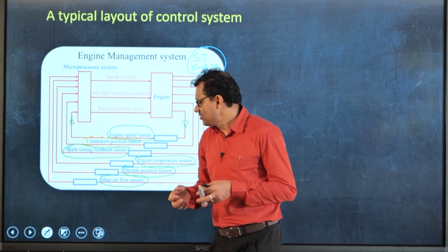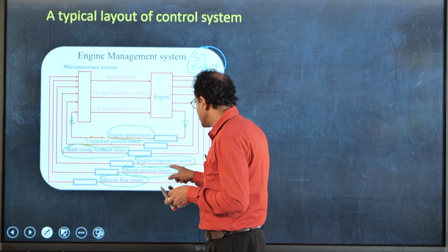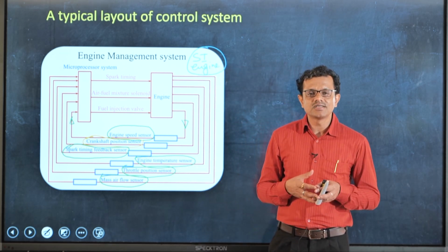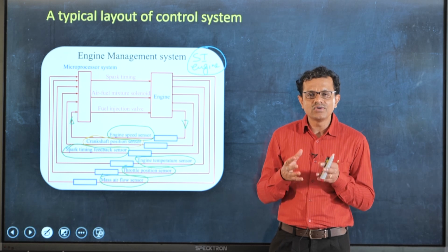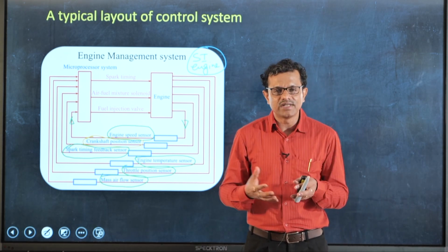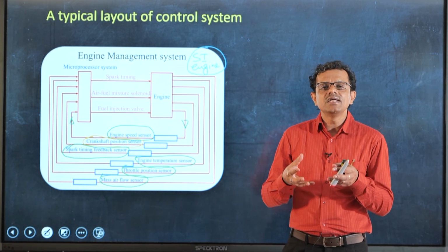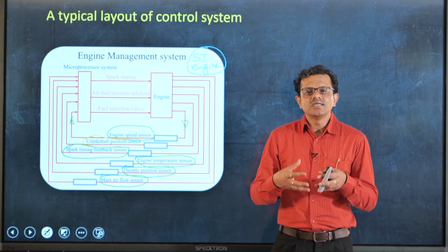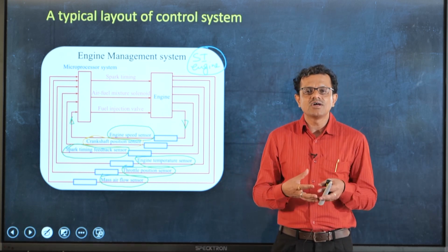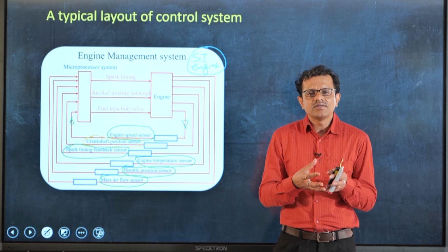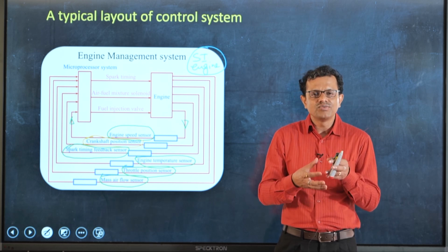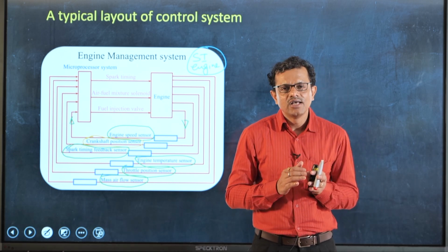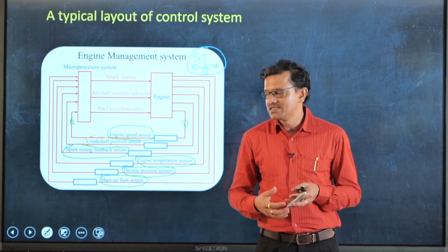To meet the demand. Engine temperature sensor, you know very well, is again a very important sensor for the modern engine, because we need to know about the engine operating condition, the engine temperature. So, sensors can be integrated into the cooling water jacket. That sensor also can be attached to the intake manifold to measure the temperature of incoming air. The air to be drawn into the engine cylinder should have some specified temperature and pressure, so as to ensure the combustion would be efficient.